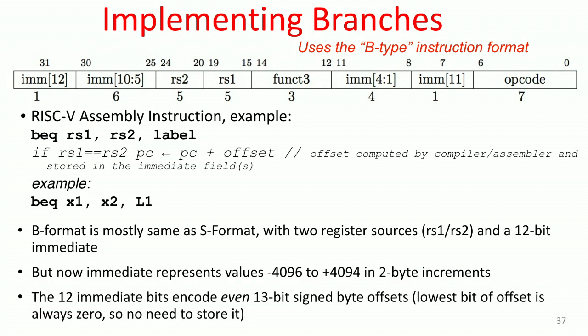And then you want to check to make sure that they're all 0. So what's that? That's effectively a big NAND. We wouldn't build it as one big NAND. We'll build it as a tree somehow, because this would be too slow, particularly for 32 bits. A 32-bit logic gate would be extraordinarily slow. So build some kind of tree of gates that has the same logical function as this. And I think that does it.